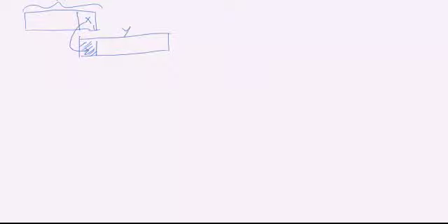Let's say Y is the next sequence. When you keep buffering, the sequence Y is actually the delayed version of X. Every time you buffer, let's say with a buffer length of 64, Y would be the delayed version of X. So you first need a delay block in Simulink to create Y from X after the buffer.